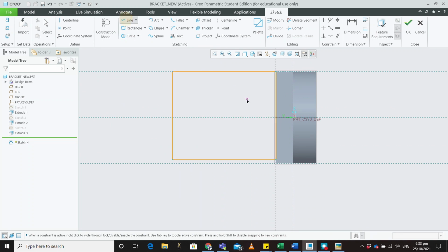And then we can draw a line for just our reference, which is at 50. So we can draw that circle. You can make use of arc or any other command, whatever you find easier at that particular point. I find that the circle would be easier for me, and it made me realize the problem that this line is not till the very end.